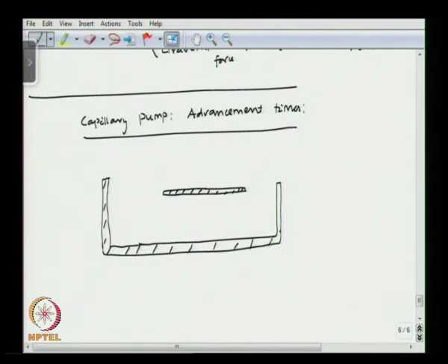Okay. So, this is the channel wall. Here we consider this to be the interface at the inlet, which is flat. Let us consider the pressure here is P0, the atmospheric pressure. Since the interface is flat here, the pressure here will also be P0. Let us consider this to be the Z axis, and this is the X axis. This height here is Z equal to H. Here the pressure will again be P0 because this is ambient, this is the liquid, and on this side the pressure will be P0 plus delta P. This is the pressure that is pushing the liquid on this side.